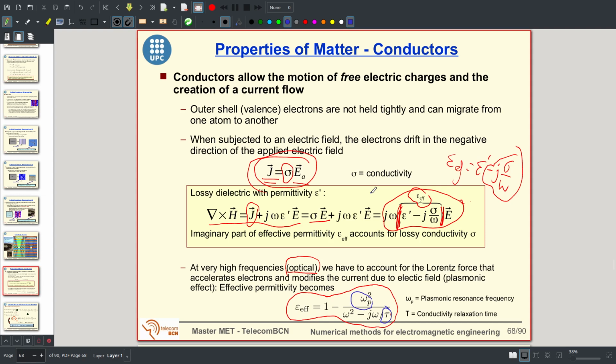I can give you information about this if you are interested, but from my engineering point of view, the only thing that is important to us is that we have an equivalent epsilon or effective permittivity given. It is also complex. It is given by a different formula from the conventional effective epsilon for a conductor at low frequency. Low frequency in this case is radio frequency, but for optical frequency the formula is different. Okay, this is the only thing that you have to know.